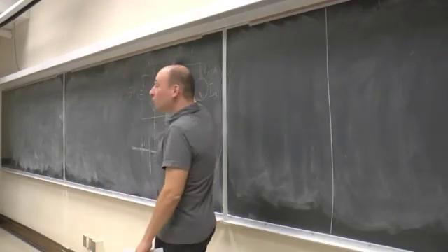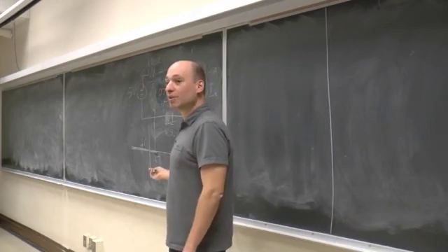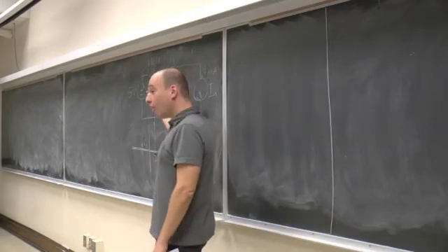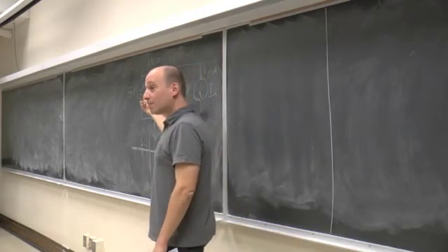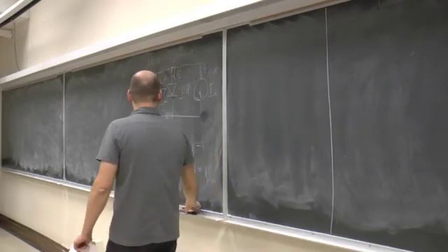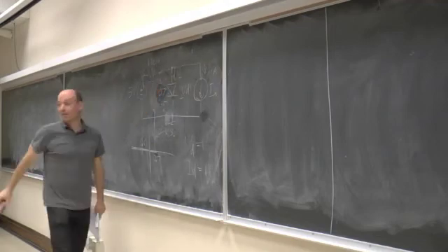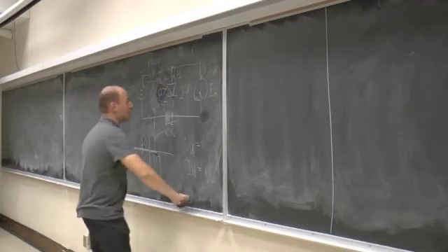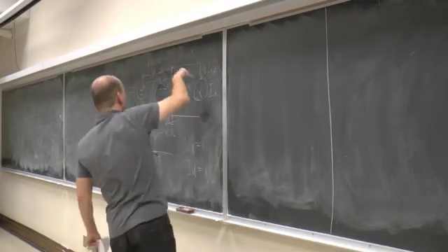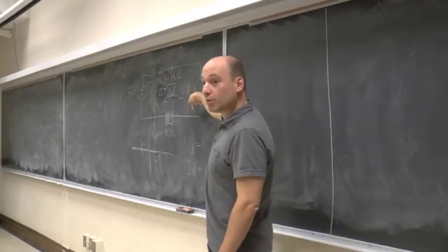What was the 1 volt based on? It was based on an assumption. What was the assumption for the 1 volt? That the diode is turned off. Is that assumption true? No. That assumption is not true, so that voltage is not true. The assumption was that the diode is off, and all the current through the resistor is driven by that current source.